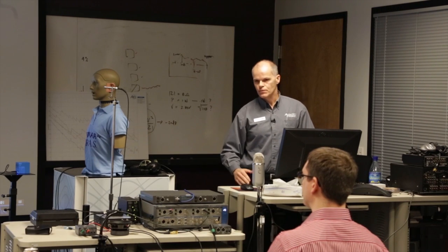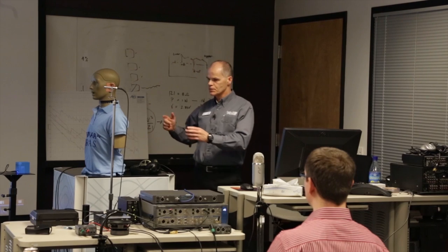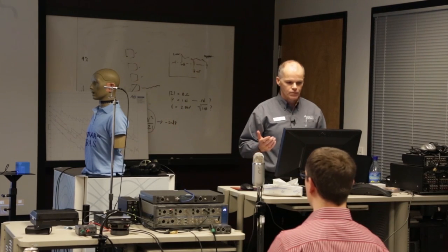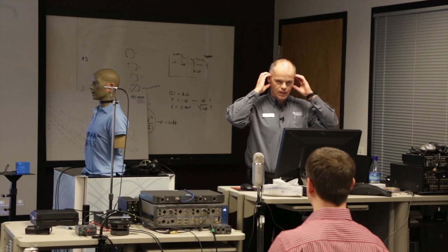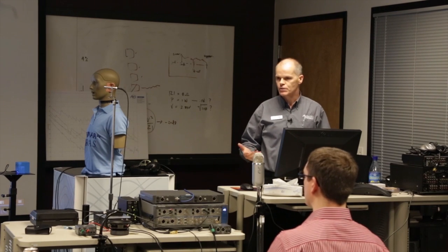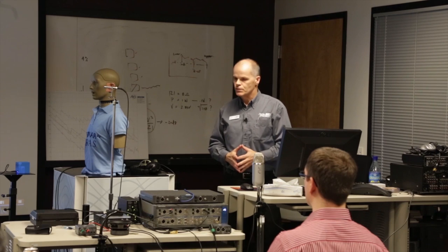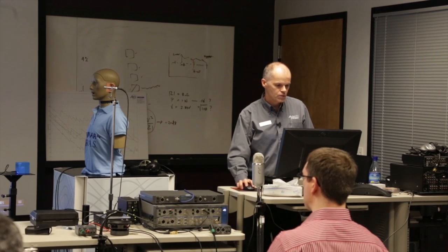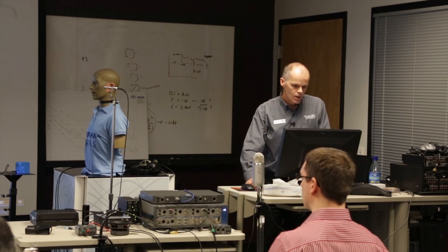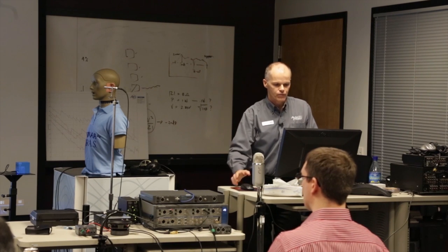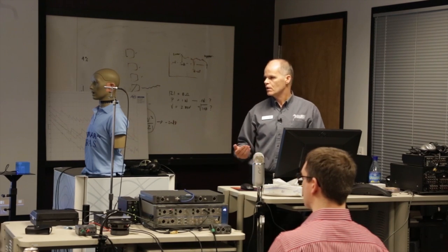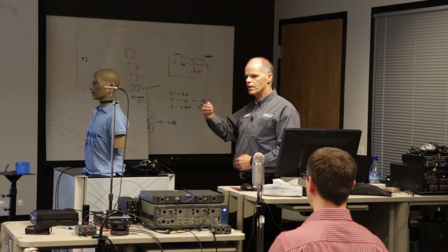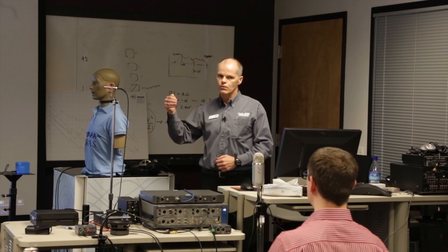I get asked the question sometimes, I've had customers say, well, I want a separate calibration for the left ear and the right ear. Well, when you're using headphones, quite often just the effect of positioning the headphone on the pinna has more effect than the calibration difference between the left ear and the right ear. So it doesn't really make sense. There is an IEEE standard, P1652, that covers this. And they use the concept of the orthotelephonic reference. So in a telephone conversation, the reference measurement is from a person talking to a person listening, facing each other 1 meter away.